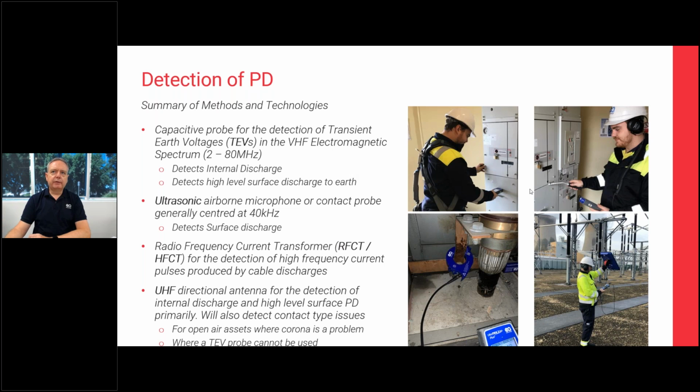Ultrasonic microphones are used in the top right picture, either an airborne microphone, which we're showing here, or a contact probe, which is also used. That detects surface discharge activity on air insulated components, so tracking across the surface. So we always use those two techniques.